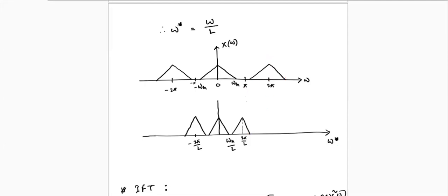Due to this shifting, you can now find that previously your highest frequency was there, the first baseband was there, and now your baseband is squeezed here. So previously, if you put a low pass filter like this, and you put that same low pass filter here, what will happen? You are getting some extra signal.